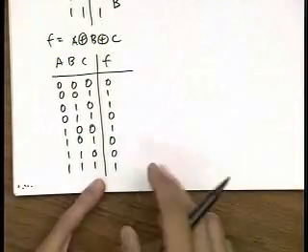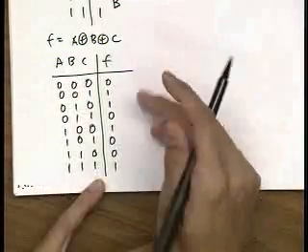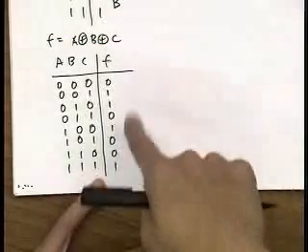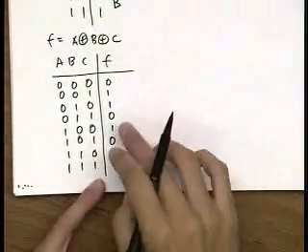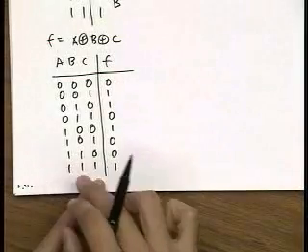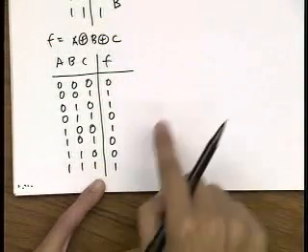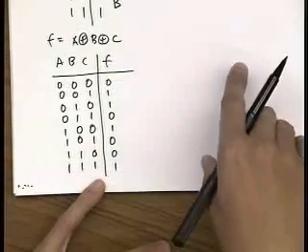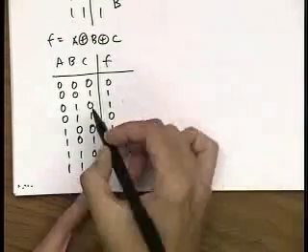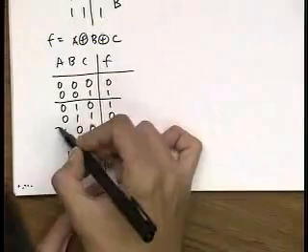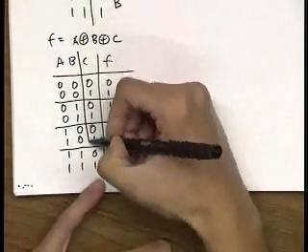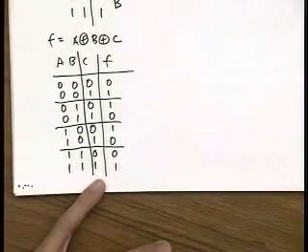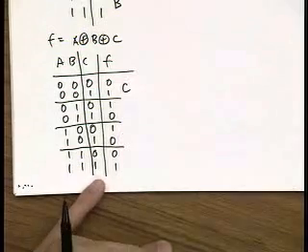Which is what you'd expect, because if you have a full adder, this would be the sum function, right? So you want to reduce the number of input variables, transferring one variable to the input of your multiplexer. If you notice that, you can break this up into this function. When a and b are both 0, the output will be equal to c.